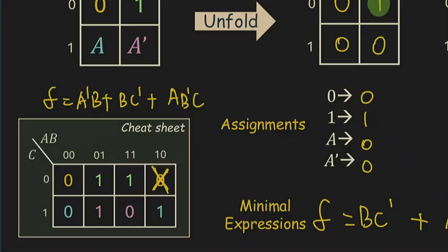1, 1 becomes a 1. What does 1, 0x become? Yeah, 1, 1 is a 1. What does 0x become? We don't know. We don't have a solution yet. You can call that a 0, right? It's valid, but you're losing minimality, potentially. Because sometimes you might want to cover this x, use it as a 1 to find the minimum expression.